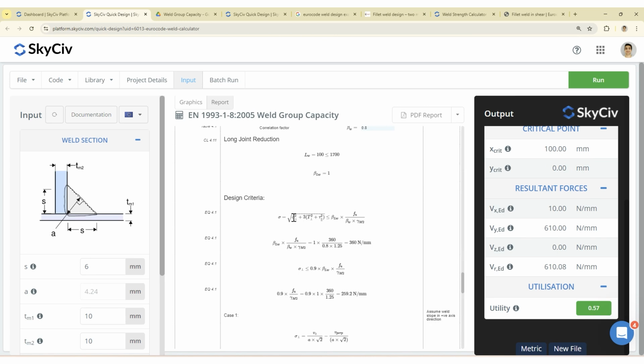we're basically simplifying this equation so we're not having to look at all these different stresses. We're just simplifying this to have these stresses all have that same 3 at the front. So it makes calculations a lot easier. We don't have to look at the stresses, but of course it's less conservative because we're trying to make these stresses less than our strengths. And if we put a 3 here, it's going to make this equation larger than if we didn't have a 3 here. So this is only going to affect us if we do have normal stresses that are perpendicular to